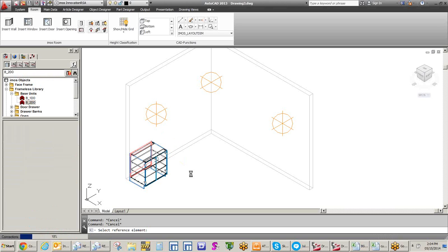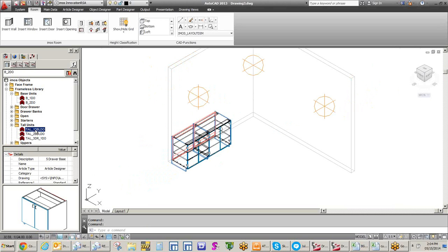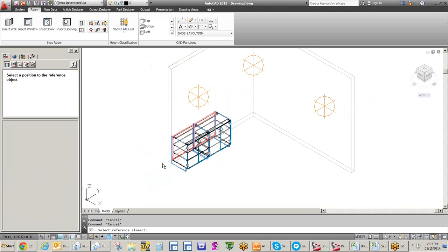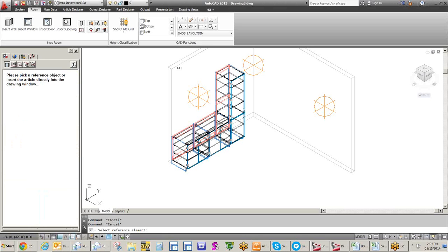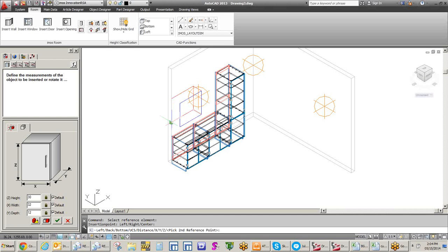And that becomes a good way to show some other examples of things that might work out really well when placing it. Then I just move on to other categories. I usually place a tall cabinet to the right-hand side of this, and then I move into the upper cabinets. Now I'll tell you, I do a little trick here that you might just want to see what I'm doing. Instead of actually trying to mess with its height and stuff, I'm just using the nearest command so that it's locating it on the wall in such a way that it gets it about the height that I want it to be. And so then I say okay to that.